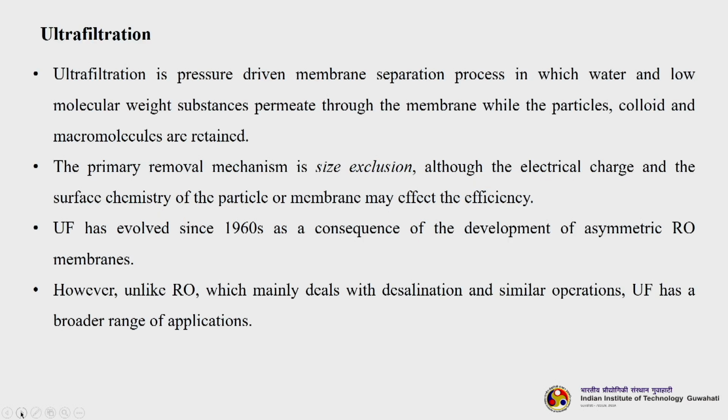So, as you know, it is a pressure driven process in which water and low molecular weight solutes permeate through the membrane, while the particles, colloids and other macromolecules are retained or rejected. So, the primary mechanism of ultrafiltration is size exclusion. That means basically it is size based separation, although electrical charge and surface chemistry of the particle or membrane may affect the efficiency also.